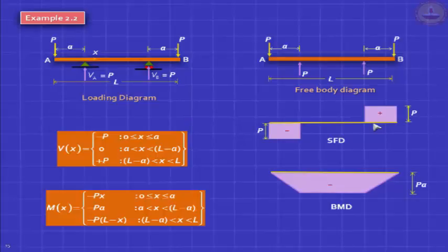Shear force diagram is like this. There's no shear force in the middle region. And in that very region, the bending moment is constant. And where the bending moment is linearly varying, the shear force is constant at this end. Right? We'll derive this later, but the broad principle is here. This is going to stretch like a circle.